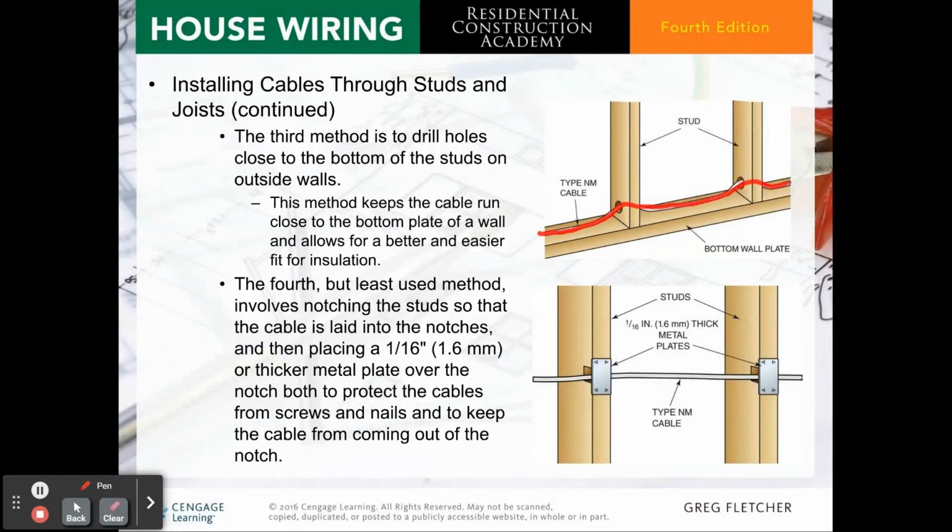right up. The fourth but least used method involves notching the studs. So again, here's your notch. And because it's less than 1.25 inches, you need to have your protector plates here that are at least 1/16 of an inch thick.